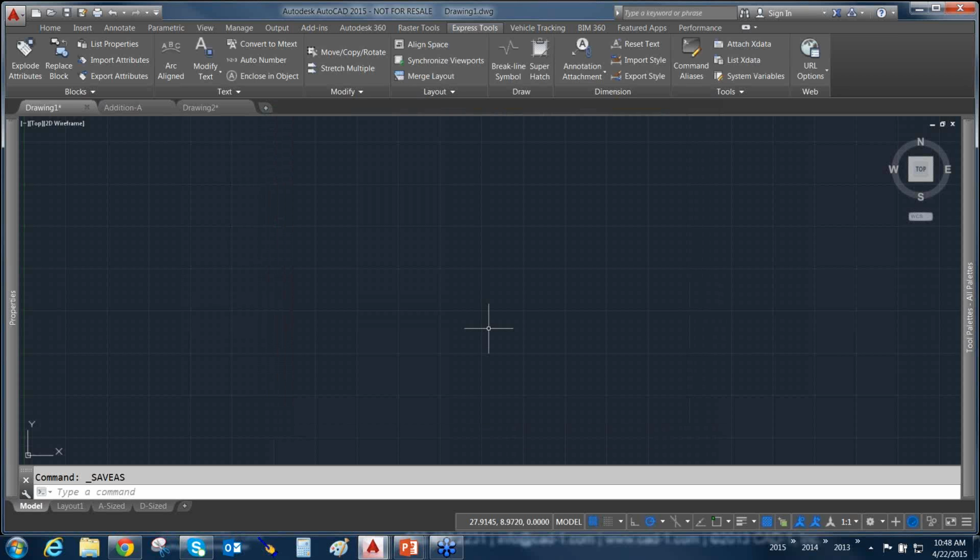Templates are just like AutoCAD drawings. They're always upward compatible. Here's the only trick with migrating templates and going forward with them. It's a nice clean template. You can use it from here on out. However, if Autodesk invents something new that wasn't in your old template, you're going to have to open up that template in a new version and make the setting change there.